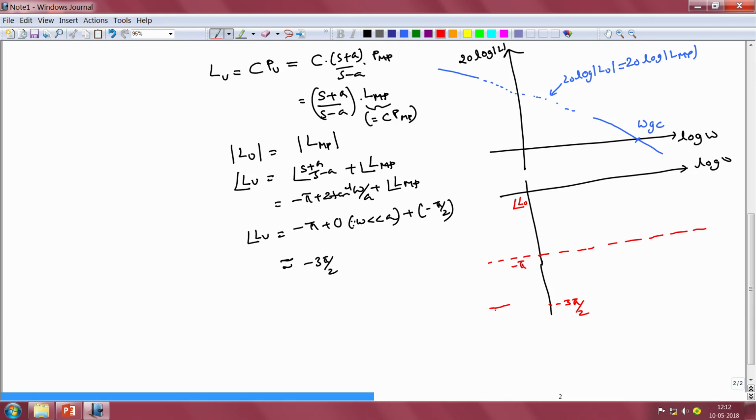on the Bode plot. So the phase starts somewhere here, and you notice that as the frequency omega increases, the phase lag of the Blaschke product starts to reduce. It starts at a value close to minus pi and then tends to 0. Assuming that our plant's dynamics have not kicked in yet in this frequency range, the phase lag will be dominated by that of the Blaschke product alone.